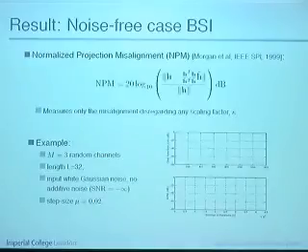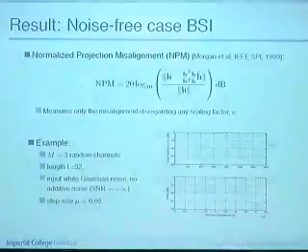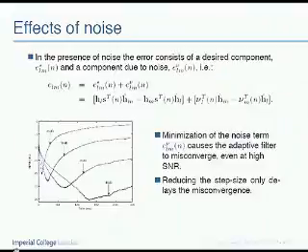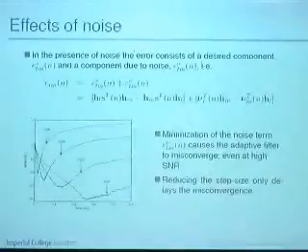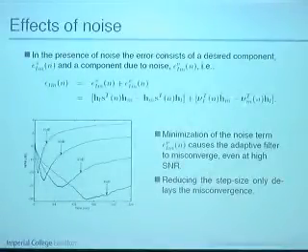However, when you try and have some additive noise, for example, white noise, the problem becomes that the cross-relation doesn't hold anymore. So your cross-relation error actually consists of 2 terms. One is the original desired cross-relation error, which is the good bit which we want, but there's also a component which includes the noise and the channel estimates.